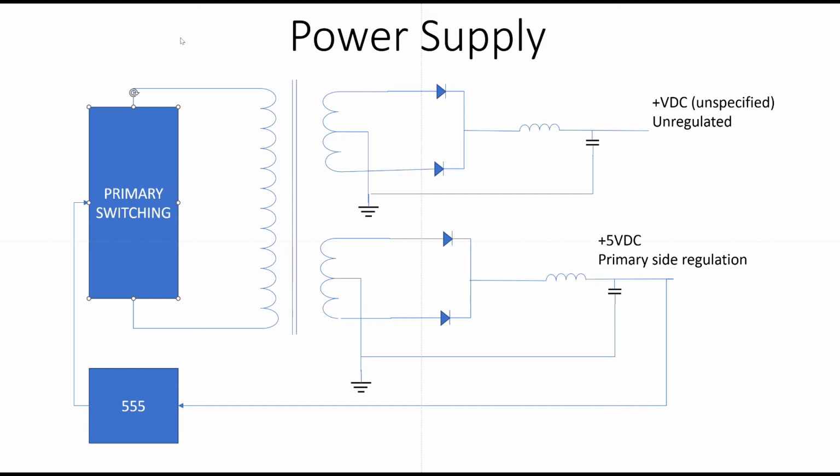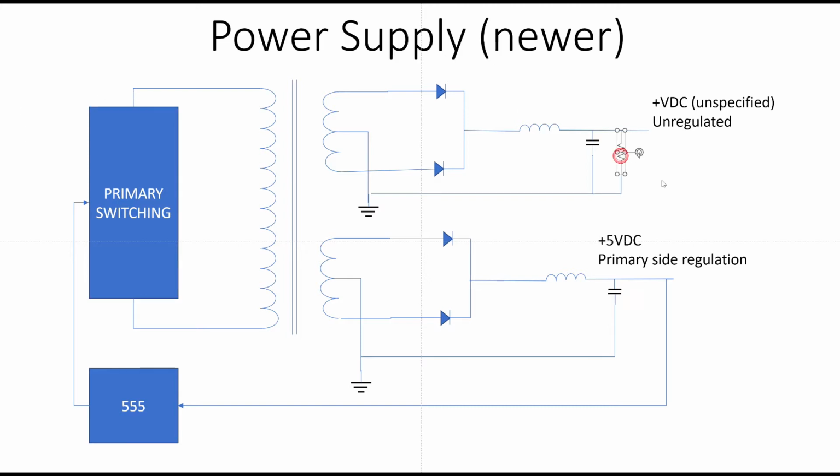So the difference on the new one, which I hadn't spotted, is a single resistor right here. There's one of those on the plus volts DC, one on the minus volts DC, and one on the minus 5 volts, and there is not one on the 5 volt plus DC side, because that's the regulated actual output. So the 5 volt is exactly the same as I just described, and the higher voltage, let's say our 15 nominal volts, has this bleed resistor on it now. So we get our pulse of power, which is really, really tiny, coming through. It gets stored and it gets bled away almost immediately. So this never has a chance to rise. And that bleed resistor is what's making the voltage stable when we actually apply some load to the 5 volts DC.